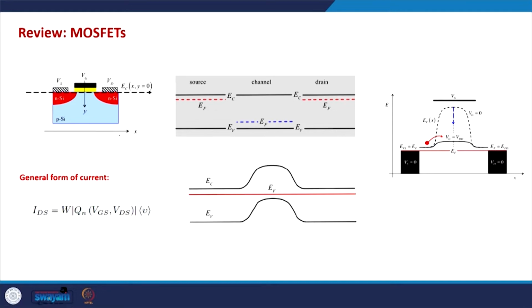So this is a typical MOSFET transistor device. This is an N-MOSFET, which means that the channel or the conducting part of the MOSFET is an N-type channel that is formed between two contacts, the source and the drain contacts, and everything is sitting on the substrate or body.